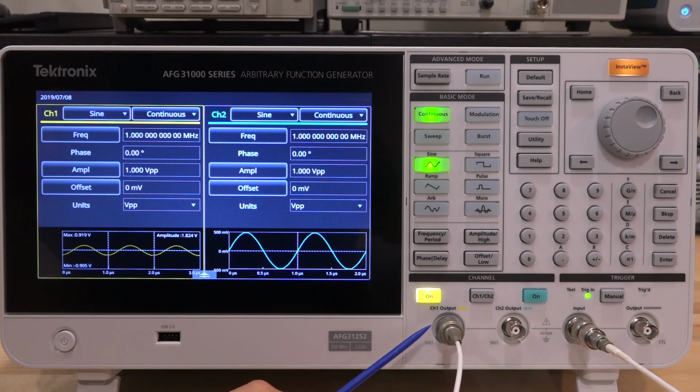I can understand why a mechanical relay is used, because you don't have to worry about the nonlinearity and all the problems that come with having a solid state device. But at the same time, every time the signal changes, it's going to click back and forth a few times, make those measurements, and that can age that relay over time. So as long as it's not running continuously with a constantly changing impedance, it shouldn't be an issue. Just keep that in mind that it will be clicking left and right every time the impedance here changes.